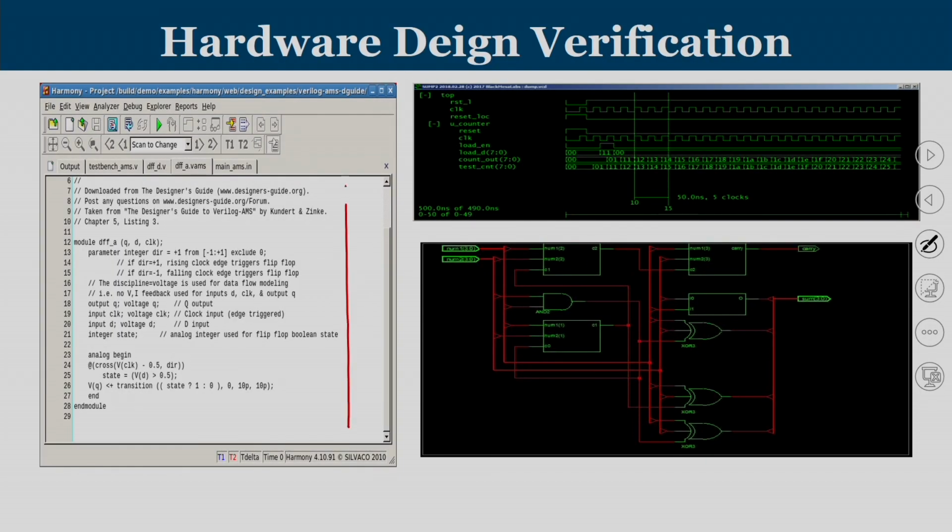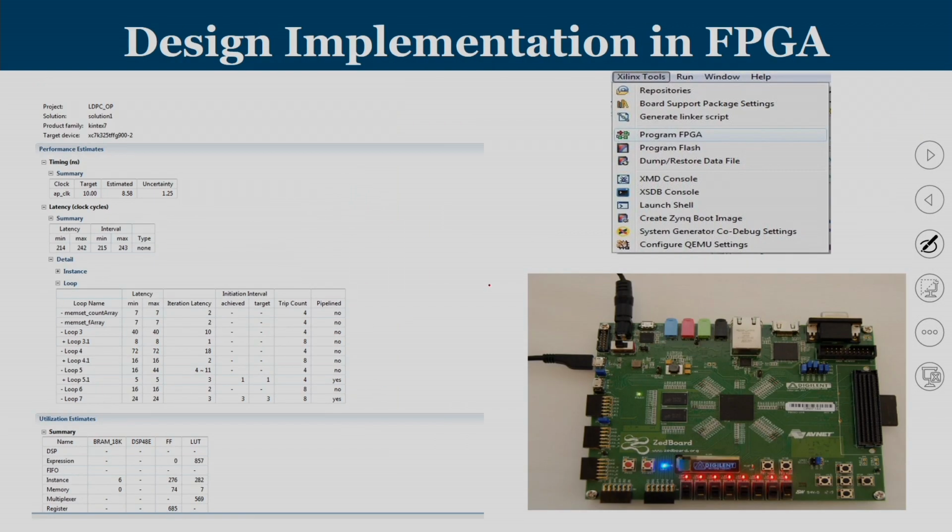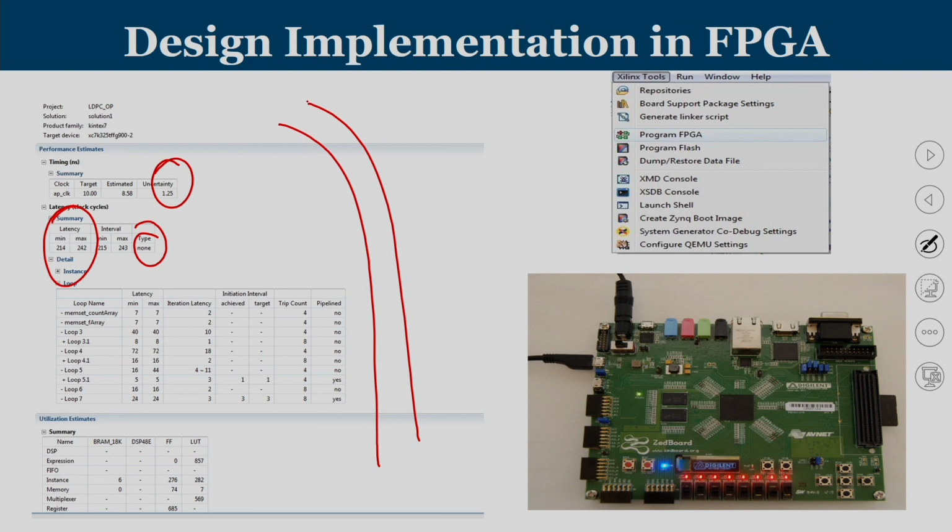You have to write your Verilog code inside some of the ISE tools, and then you synthesize and verify whether all the output signals that you are having happen in the proper timing cycles. Generate the gate list. So, this is the equivalent gate level circuit of the code that we have, and then you get the synthesis report. How much is the latency, how much is the area, the type, the number of various subunits. So, this is what is known as a synthesis report, and that will tell you what hardware components are used, and then you generate the bit stream.